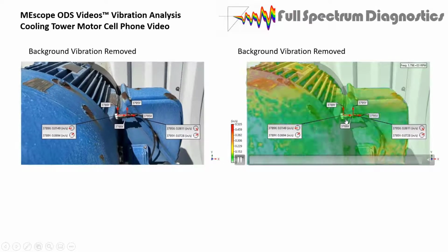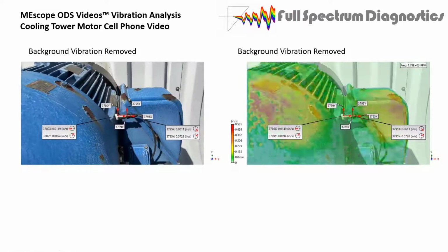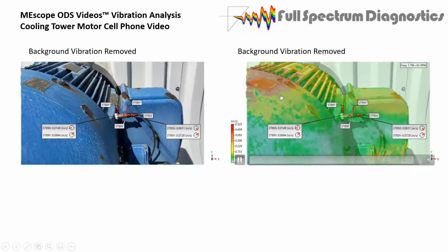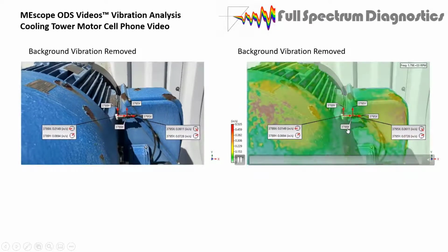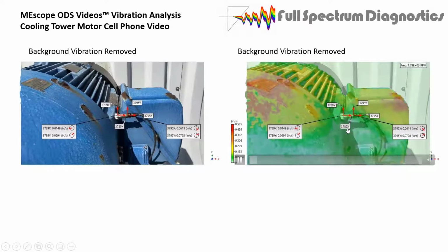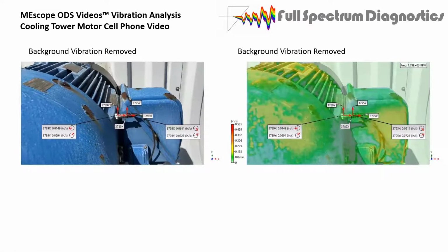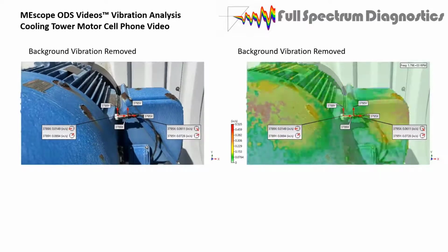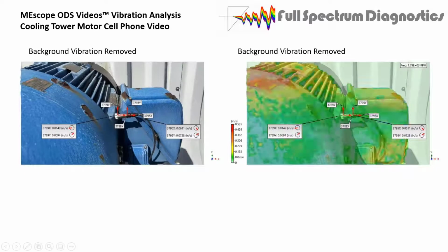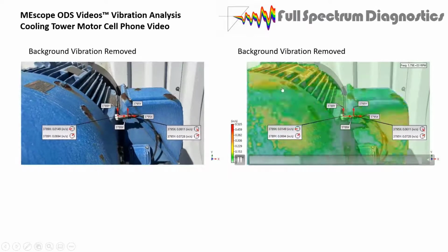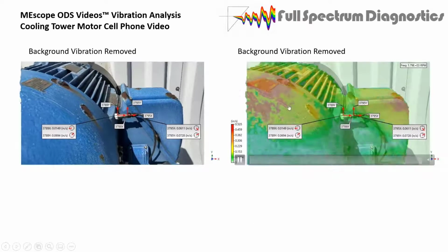But what we're normally route-based trying to discover is not natural frequencies in the end bell or problems with the connector box. We're looking for a transmission path to the bearing. So the bearing defect frequencies are one of the big flaws that we're looking for in walk-around route-based vibration analysis. In this case, it turns out it's not the best place for visually looking at the vibration. Okay, but it's interesting nonetheless.